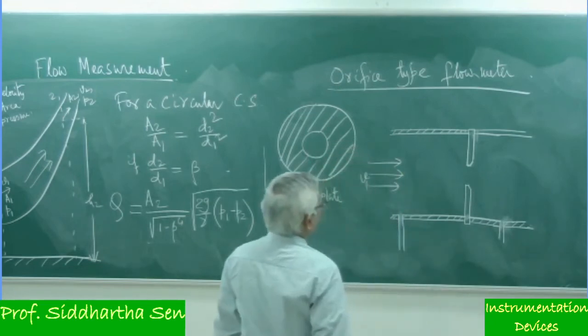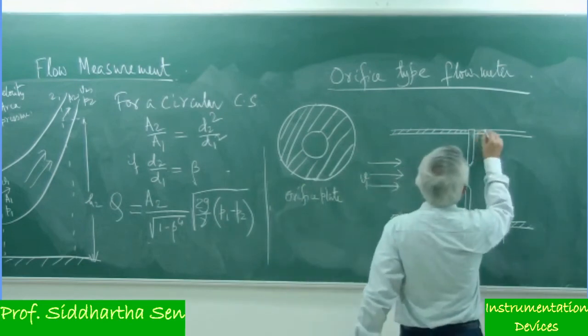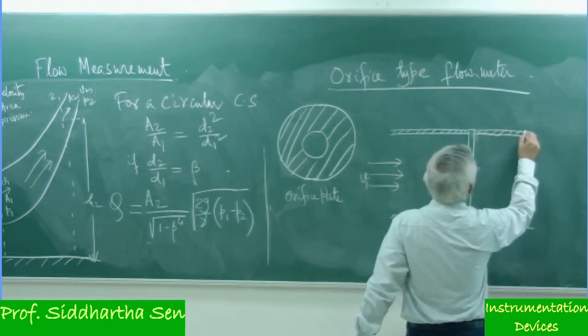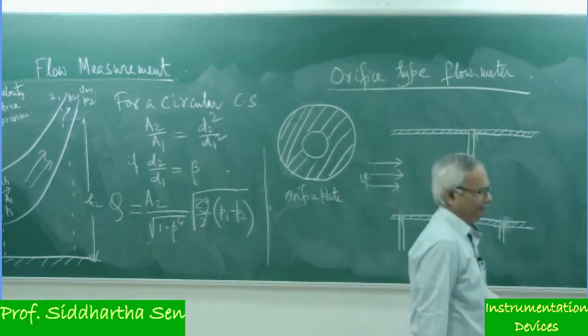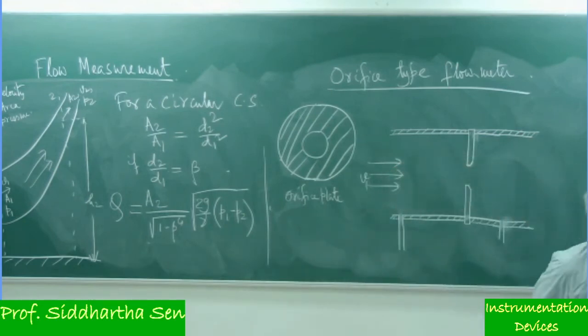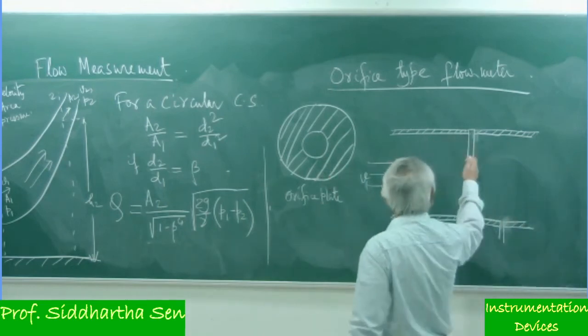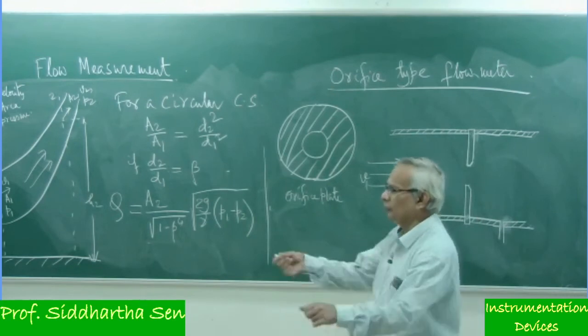What we do is, this was a pipeline, and here in the pipeline I make a break. I just cut it and I insert a very thin orifice plate into it and then bolt it properly.